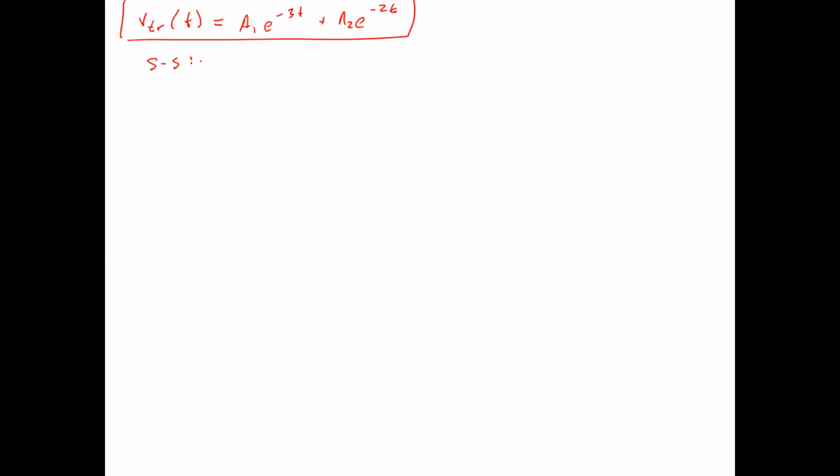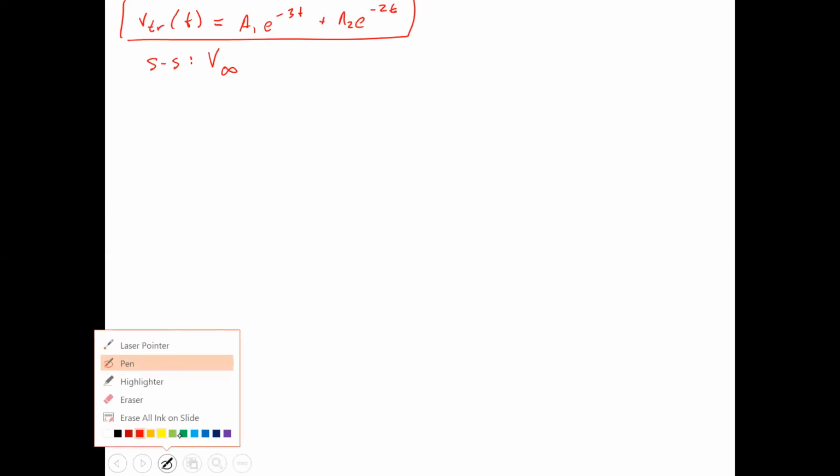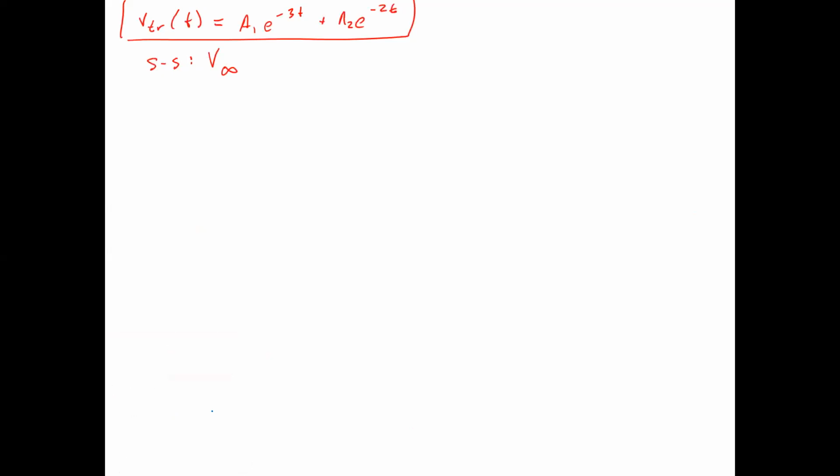But that's just part of the solution. We also have to consider the steady state, which is the infinity, the final value of V in this circuit. And the final value of V is going to be looking at that circuit long after everything is stabilized.